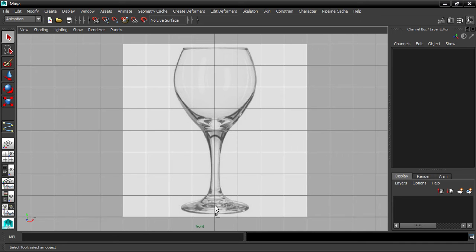Your object is going to have holes in it, or even worse, it's going to have self-intersecting surfaces that pass through each other, and it's going to be horrible. So in order to control this in Maya, you need to know that the curve needs to be exactly at the center of the world, and there's no mercy around this. And you can't do it any other way. It has to be done this way. To make that a little bit easier, you can use snapping to the grid.